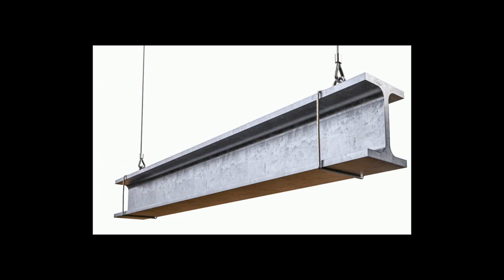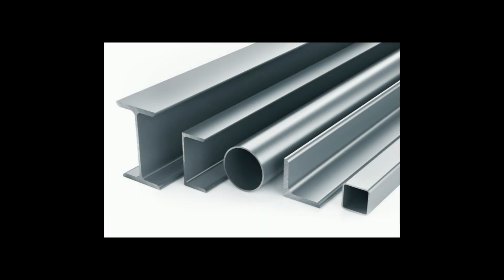Every piece of steel used in manufacturing has a cross-section, or profile. The profile determines the item's section modulus, a key factor in structural strength. The shape, represented mathematically, is an input to determining the rail's resistance to bending. This concept is fundamental in truck engineering, allowing for comparison between different rail profiles and ensuring the right selection for each application.